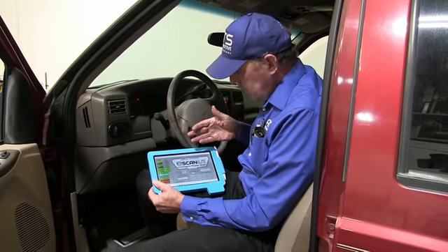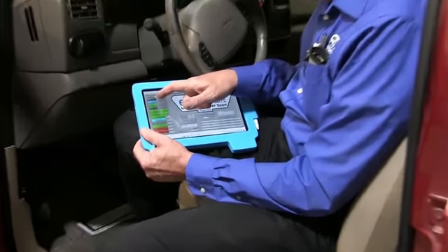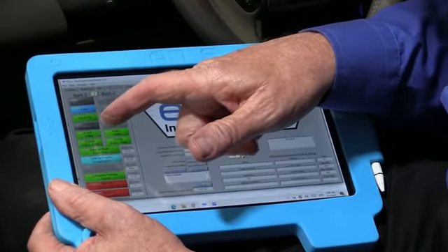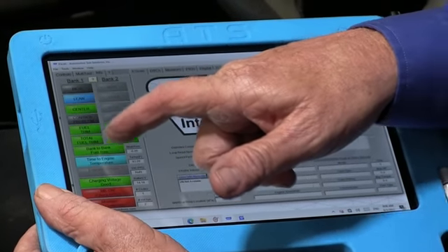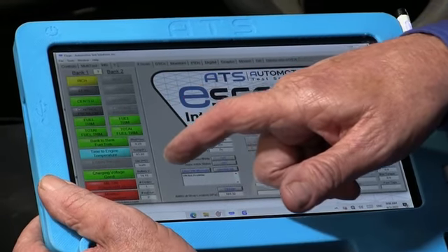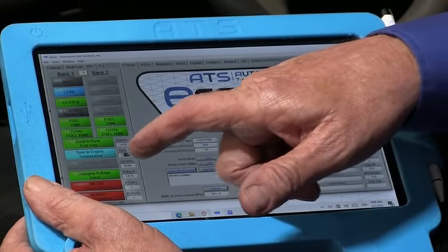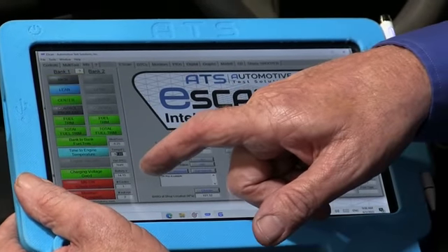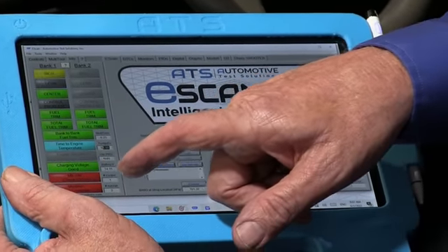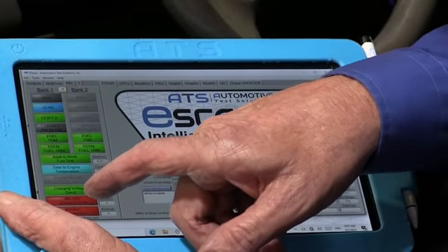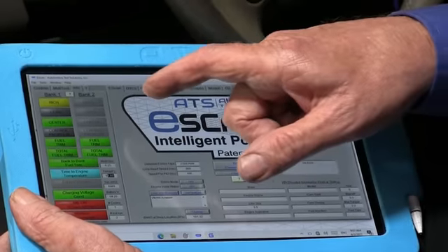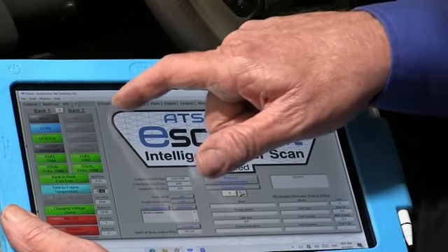Okay guys, I got the scan tool up, we've got good fuel control, we're switching, we're centered, and the long and total trim are both good. Bank to bank is good. We just started it, so we're warming up still. Charging system is good. We have a code set and the monitors haven't been run. We know that they've been working on the car, so I'm not worried about the monitor, but I do want to see the codes.